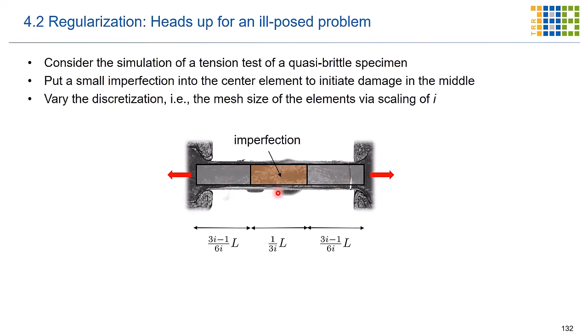And now, in the context of the finite element simulations, we want to have accurate results, and we usually tend to have smaller and smaller mesh sizes to have a better approximation of the solution. Yeah? So each element might give us an approximative solution, like a linear function. And to get a better solution for the damage distribution, for instance, we had used smaller and smaller elements to get a finer resolution.